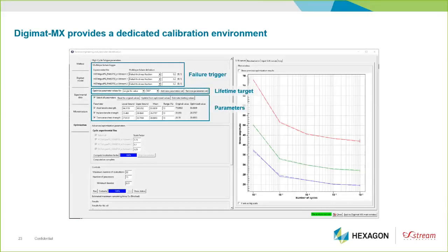You then have the parameters of this Tsai-Hill 3D failure indicator, so X, Y, and S in terms of strengths, and you have, similarly to what we do for static failure, the localization factor. So you can account for the fact that locally at the coupon, when the coupon is breaking, it is not the macroscopic stress level that is leading to failure, but the local stress, which is higher due to stress concentration at the hotspot.